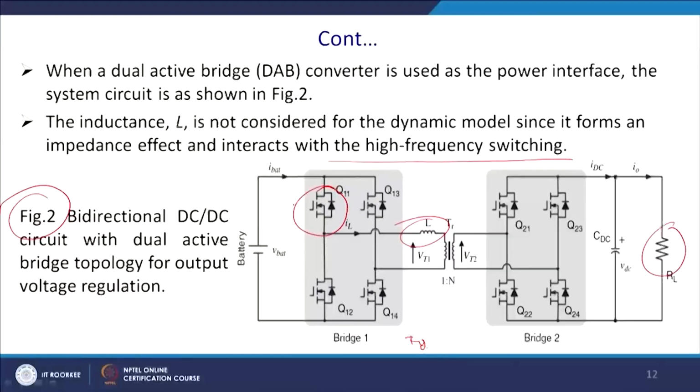If this converter is IGBT based, then it can handle power up to 100 kilowatt, and of course, the switching frequency is required to be lower, and ultimately you may also be operating a few converters in parallel, which also needs to be taken into account. And while designing, this battery will give you the intermittent extra power required from the solar or this thing.